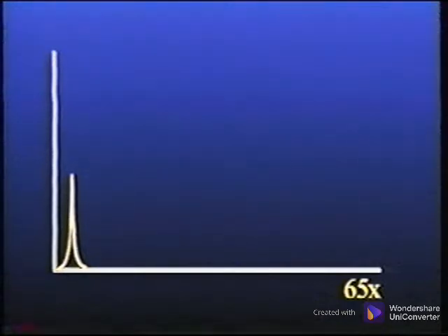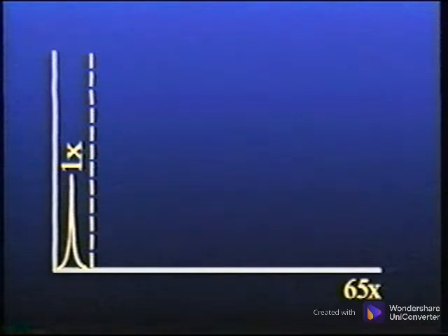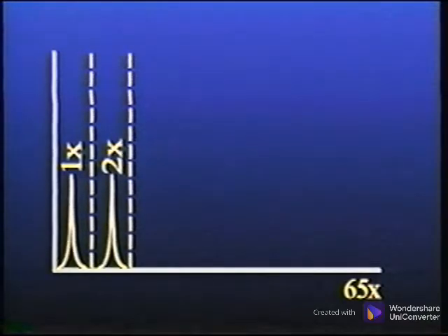The spectrum can be divided into 6 separate bands or parameters. These bands can each have its unique alarm levels. For these rolling element bearings, CSI recommends 5 spectral bands plus 1 variable high-frequency band. The first spectral band should include the subharmonics and the 1 times energy. Typically, set the cutoff at 1.5 orders. The second spectral band includes the energy at 2 orders, so its upper limit is 2.5 orders.